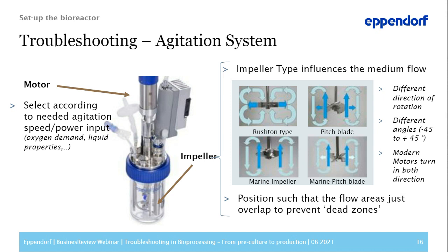So along with the shape and the angle of the impeller setup, the orientation of the impeller is also important. The orientation of the impeller, meaning whether it's a left or a right-handed impeller, and its agitating direction will determine whether the direction of the axial flow is up or down. Now, a right-handed impeller option will push the fluid in an upward direction towards the top of the vessel if the agitation is used clockwise. Whereas if you do a left-handed option paired with a clockwise agitation, it will push the fluid